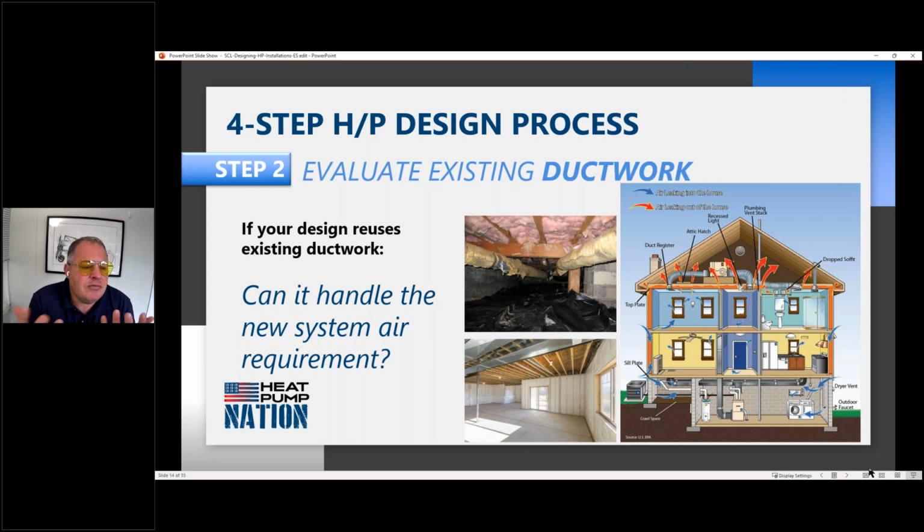That's because originally my house, when it was built in the early 1900s, had something like a coal burning system, which used very low airflow, but that's very, very hot air. And heat pumps use more air, but the air is not as hot as an oil furnace. So oil furnaces are renowned for having 140, 160 degree discharge air. I mean, it's extraordinarily hot.